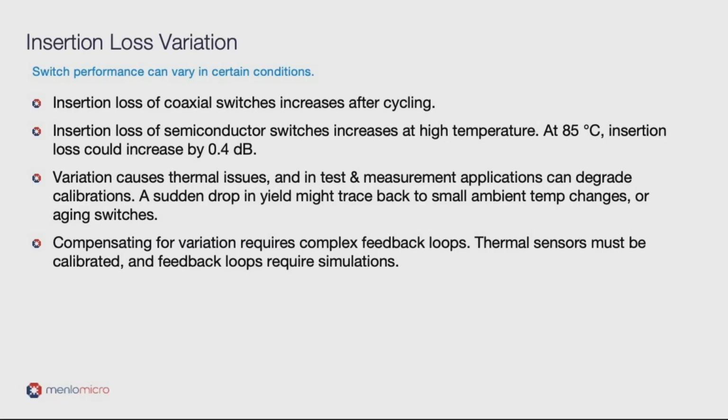Variation causes thermal issues, and in test and measurement applications can also degrade calibrations. So a sudden drop in yield might happen on a particularly hot day in the lab, or as the system ages, the yield of the devices under test will steadily go down due to these changes in insertion loss.